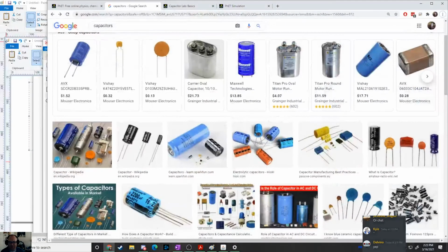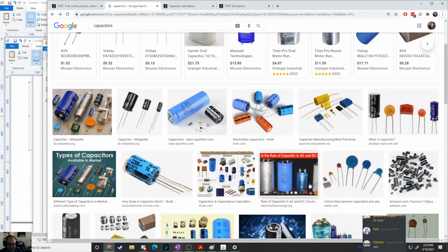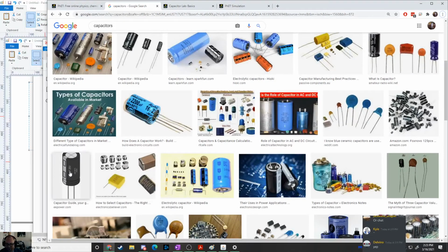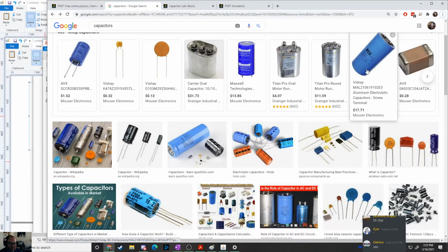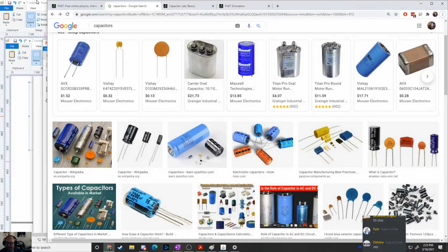I don't know if on this picture we can see, but you can see it on this one here. You see how it says 2200 microfarads, and it looks like there's a temperature range from -40 to plus 85 degrees Celsius. And this is a polarized capacitor, which means that I believe this has to be the negative side. But they'll usually be labeled on the actual device what the value is. This one looks like 1,000 microfarads. So microfarad tends to be much more normal. That's 4,200 microfarads. We have some in the lab that look like this, and they are like 6,000 microfarads. I think it's the biggest ones we have in the lab. So a 1 farad capacitor would be gigantic.